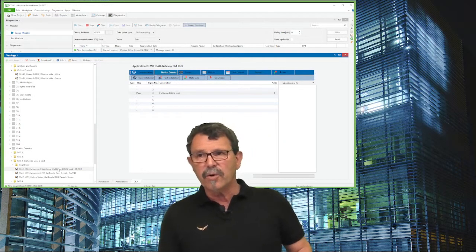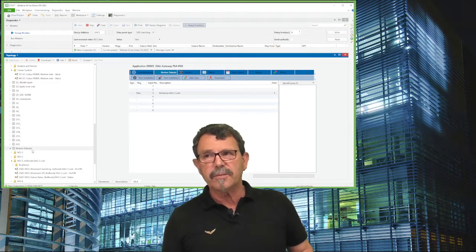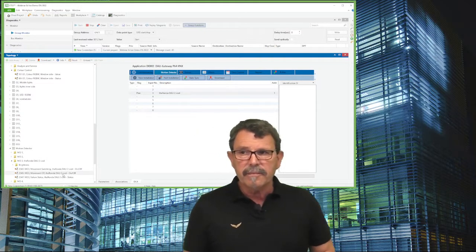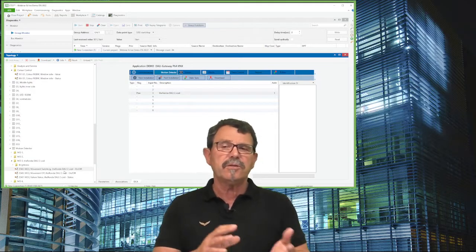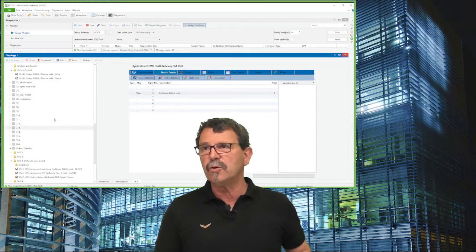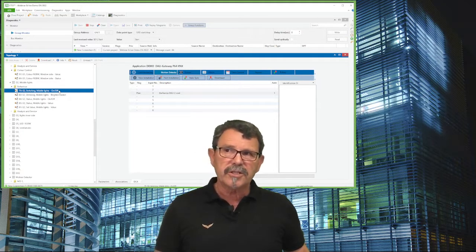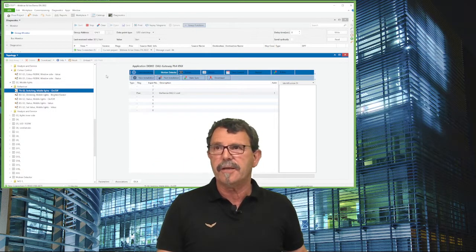And here you now discover the abilities. That means the communication which is supported by such a presence sensor. In the multi-master application it is a motion detector, but in our case it's a presence sensor. So now you can link this communication object, switching on movement or presence, however, directly to a reasonable light group, for instance, which we have here. Same group address like this one here, and so this pure DALI 2 sensor is finally controlling this light which we are displaying here. Okay? So sounds easy. It is easy.